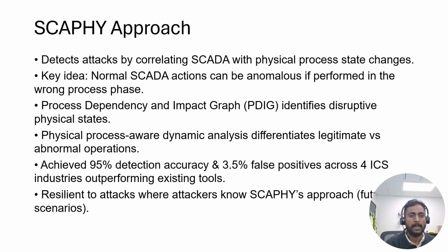For instance, let's take that example of the Florida water treatment attack. What if the sodium hydroxide level was already high, but there was a set point to open a valve? So while the traffic from the SCADA might increase the set point, the physical state somewhat deviates from that because it's already high. So what if you can model that and detect that as an anomaly? So that's kind of the approach of Scaphy, and they do this in a few steps.